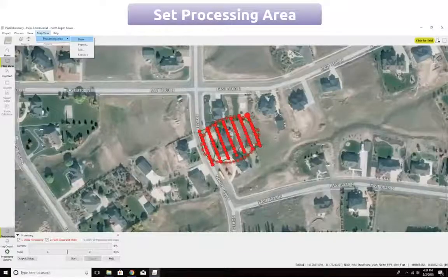So you load that up, and then it's going to pull up the map showing the locations of the images here, which are the red dots. Because they were geotagged, Pix4D knows exactly where the site is, and so it can map the location of where all the images were taken. You can see here, I actually flew two missions. There's a double grid mission, that's the bright red dots. And then you can see underneath that, I also flew a circular mission, and those are the slightly transparent red dots there.